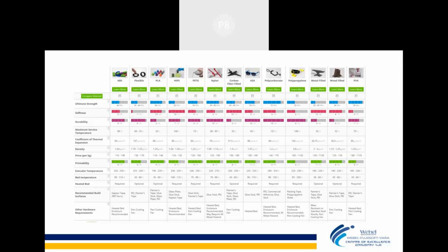Then there is a variety of materials, like nylon and polycarbonate, which are real-life-use materials, even PP and PETG. Every material has a certain temperature coefficient, density, flexibility, and strength factors. So we will use our material according to our application. What is my real-life use? What is the load-bearing capacity? After getting the final part idea, we will choose our material accordingly.